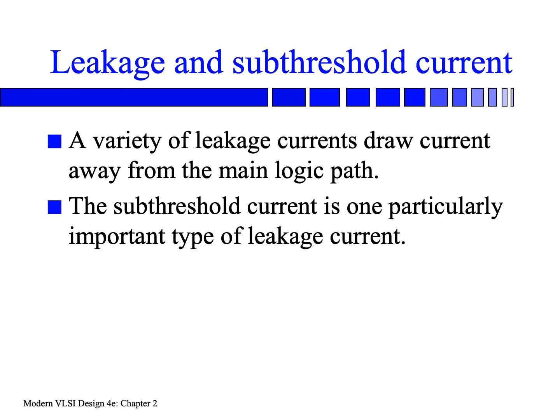Another important thing I want to talk about for transistors is that most transistors, even though they are turned off, still leak. Leakage has actually become pretty significant as technology moves to more advanced nodes. So we cannot ignore the leakage, and sometimes leakage plays the dominant role in some of the designs. I'm going to talk about the so-called near-threshold voltage designs, so we need to understand where leakage comes from.